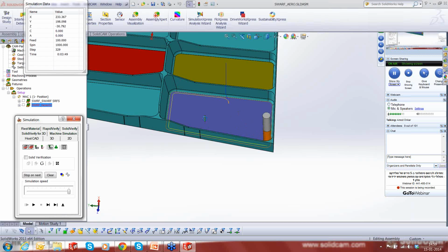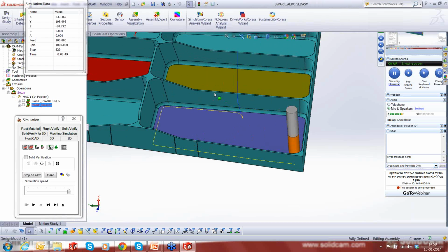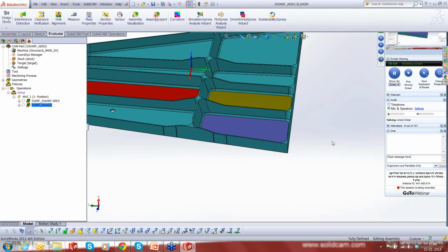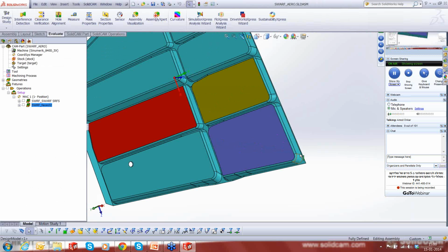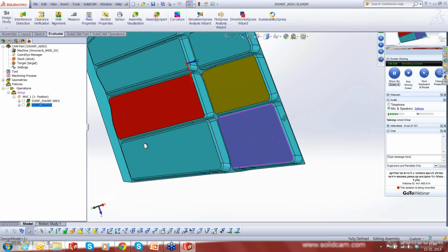And then as it comes closer into the wall, it's adjusting. Now this is a very dangerous move. Depending on the kinematics of the machine, if it's a head machine, your entire machine could take a major turn in a very short distance, and this could be catastrophic for the machine. Let me go ahead and see, because I had highlighted to you one of the problems. Let's see what is happening there. Again, it's the same thing, and it's finished. So we now know that there is some problem out in this area, and we really don't know what could be the problem.